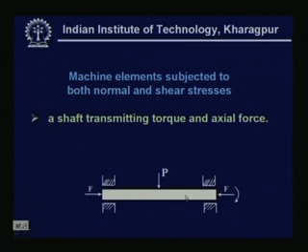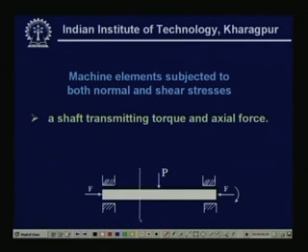There could be axial loads, and there is a torsion, that is, power transmission is taking place, and the actual load of the machine member is there, for which you get an equivalent load P. So, if you consider any section, and similarly if you take an element like this, then you get this particular type of stress element that we have seen earlier, and that will consist of what?